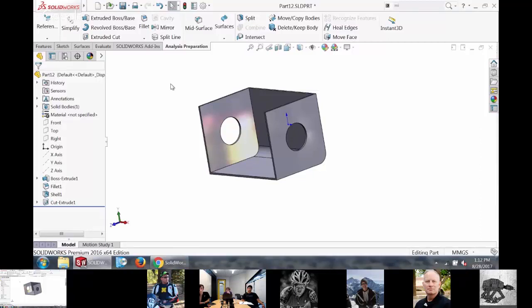There's 2 kinds of errors you can have in an assembly. You can have a rebuild error with the geometry, or you can have a mate error where it's no longer fitting together. It's, again, one of those cart before the horse type of things where if we fix the geometry, a lot of the times the mates will get fixed because the geometry is back again, where the only reason you had a mate error was because there was a missing face or something. I don't know if I answered your question, but I am going to go through these step by step to show you the methodology behind it.